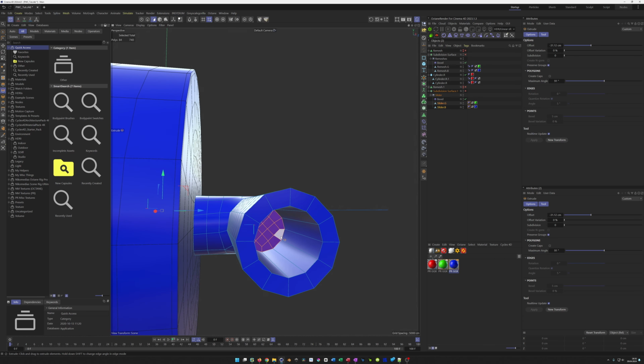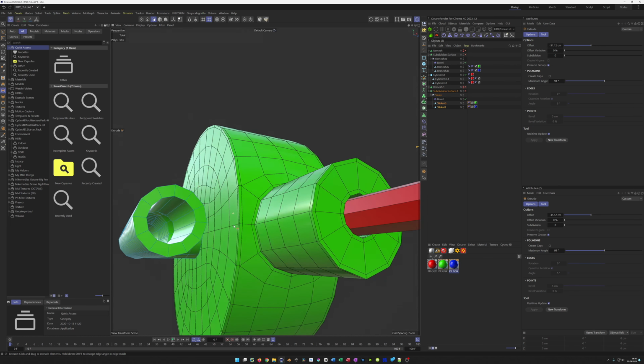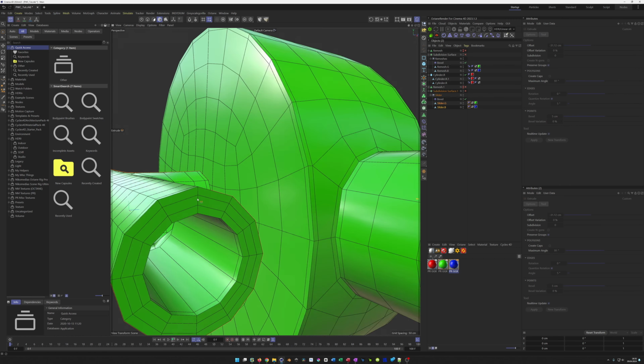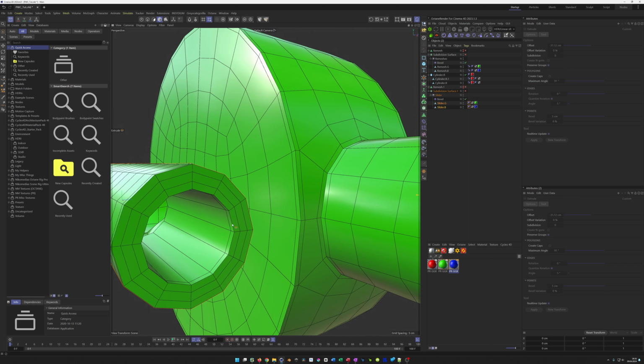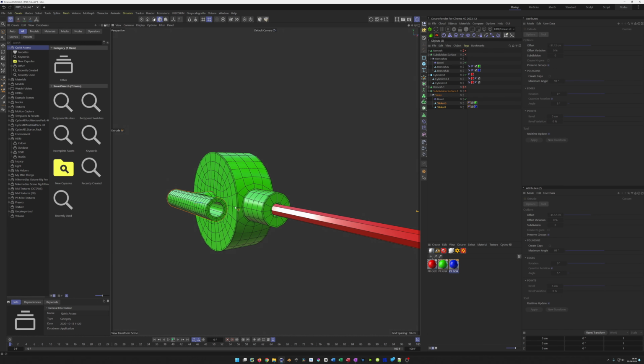We can now delete the polygons inside. Then we can change this radius whenever we want. Yeah, let's delete the polygons here. We don't see it, so it doesn't matter. Good. Here it should have the same. Perfect. When I do now 4 and go back, you see the bevel works now on these edges here as well, because we have this almost 90 degrees. So we have this wonderful smooth roundness here. Yeah, so we do a little modeling in this tutorial. But normally the modeling is not needed, since the volume builder is almost obsolete.